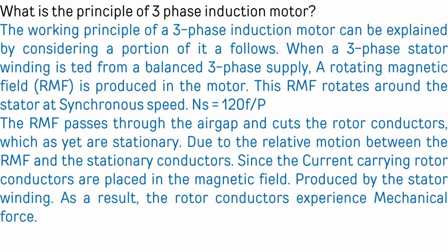Due to the relative motion between the rotating magnetic field and the stationary conductors, an EMF is induced in the rotor conductor. As the rotor is provided with end rings, a current flows in the rotor conductor. Now, a current carrying conductor placed in the magnetic field will experience a force, and the rotor starts rotating. This is the principle of three-phase induction motor.